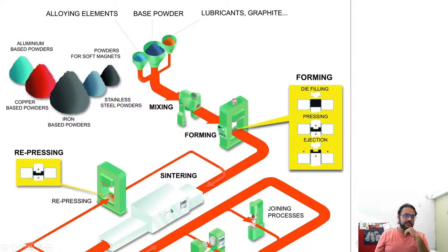Okay, and once it goes through, it is heated, and when it comes out, whatever unnecessary things there were, like binding agents, get evaporated out. The little balls of metal powder, the individual balls, kind of melt because of the heat and fuse together to form a more homogeneous part.